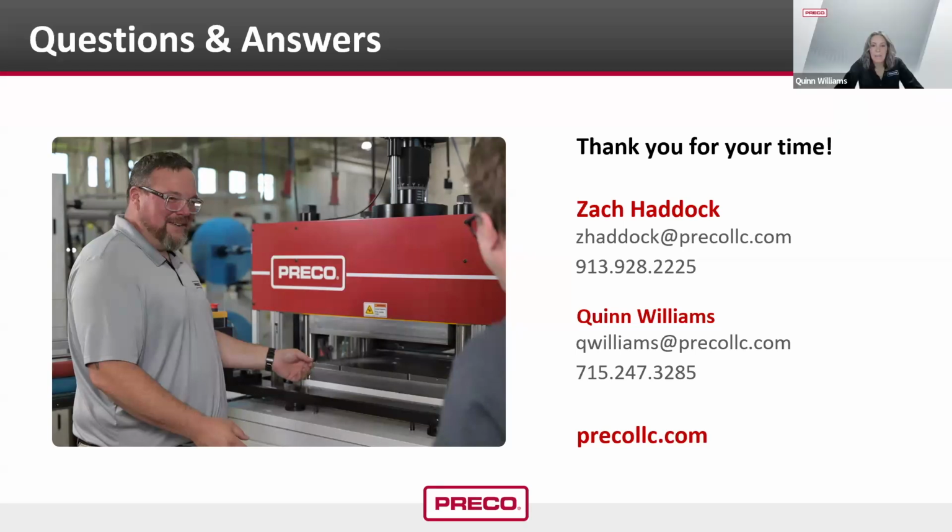Thanks, Zach. Can you make up more tonnage with dwell time? Not really. You could make the argument that maybe there's some softer materials, or there's always outliers. There's always fringe materials that take maybe a little bit extra time. But in general, if it hasn't cut, it's not going to by the time the ram cycles.